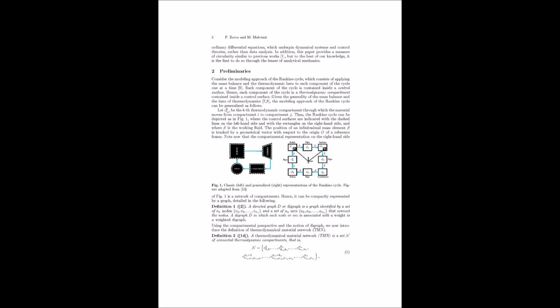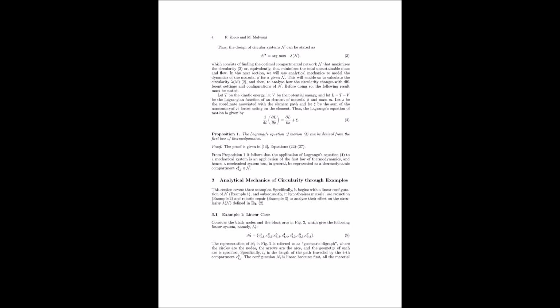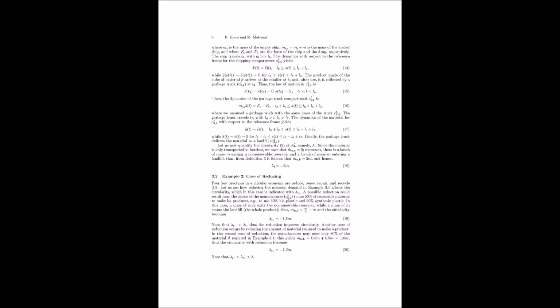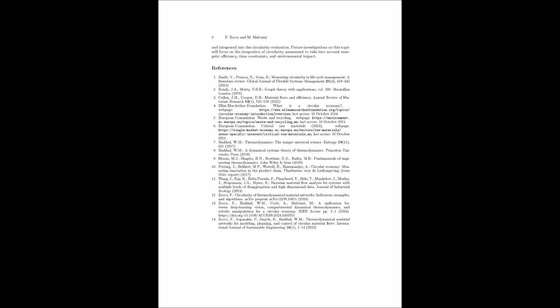Yeah, absolutely. Let's go back to that truck compartment example. So picture our cube on a flatbed truck just cruising along at a constant speed. Okay, I'm picturing it. Nice straight road, truck moving along. What happens next? Okay, so to use Lagrange's equations, we have to define what's called the Lagrangian of the system. It's just the difference between kinetic energy, which is T, and potential energy, V. Okay, so L equals T minus V. Yeah. Got it. What are the kinetic and potential energies in this case? So the kinetic energy is easy. It's just the energy from the cube moving. Since the truck's going at a constant speed, we can use the regular formula: 1/2 times m times v squared, where m is the mass and v is the velocity.